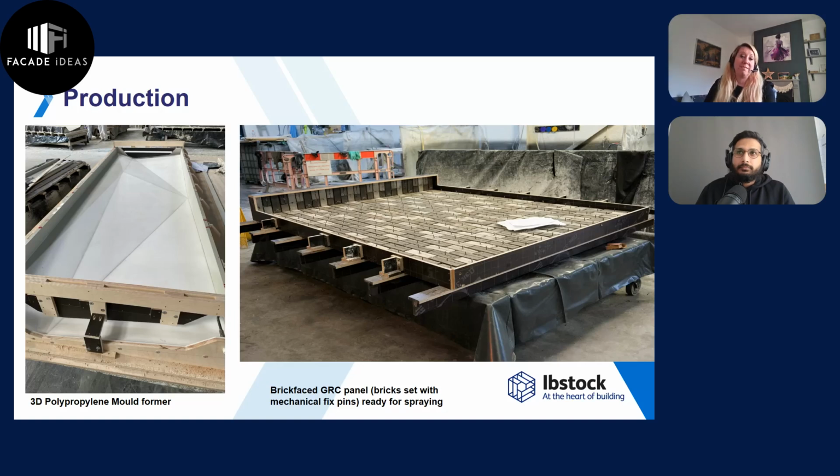So we've made the mold in exactly the same way, and we've placed those slips face down into that mold, and you can see there that we've got some sort of groove in the back of all those slips. And as I've said, a slip is not just a slip, and you cannot use the same slip for every product. So there's a particular notching that we use for this product, and that allows the GRC to then flood into that and tightly secure it into place. But in addition to that, for extra security, we have this metal pin that also attaches itself to the GRC mixture. And you can see there we can also do returns on this particular product too.